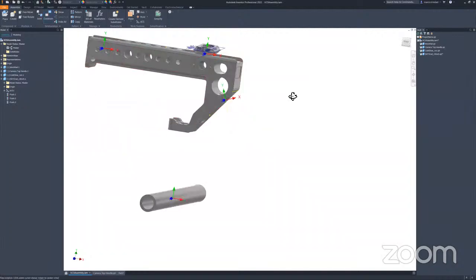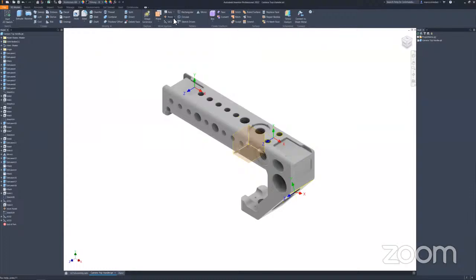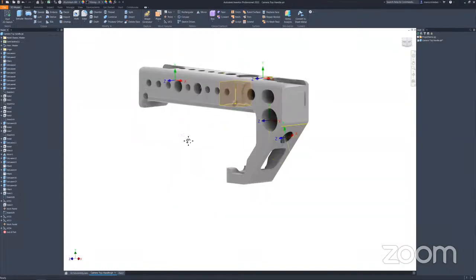Need to place one on this hole right here. Go ahead and place back to the handle and quickly place one point and the UCS. Yeah, it's interesting to note, because when you do the UCS to UCS constraint, that's going to fix it in all three directions, correct? Like it's going to be completely fixed to that orientation.